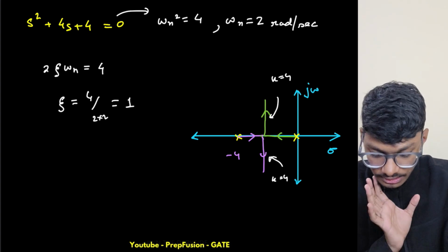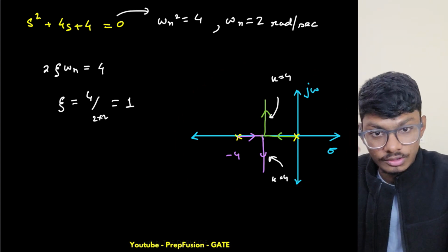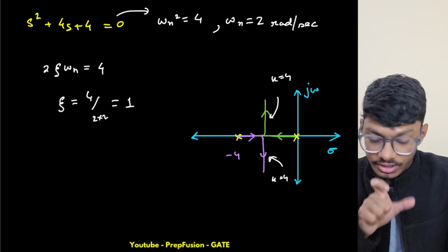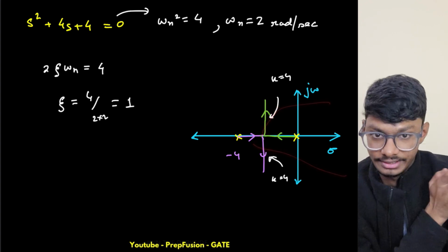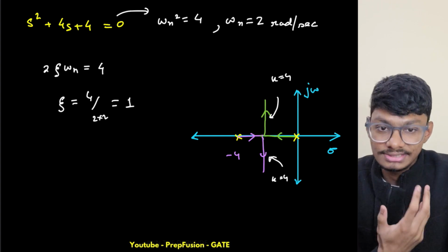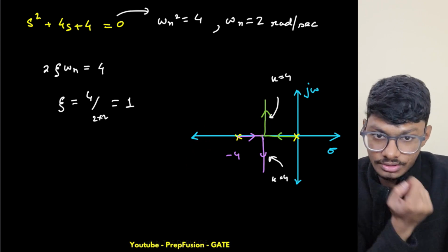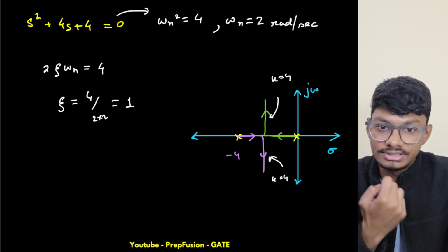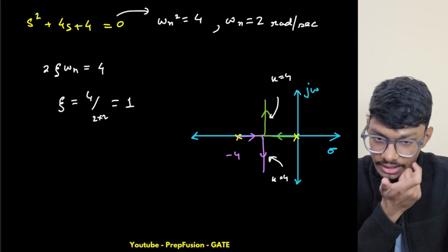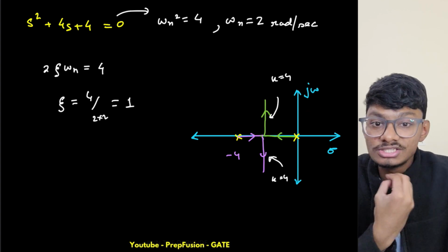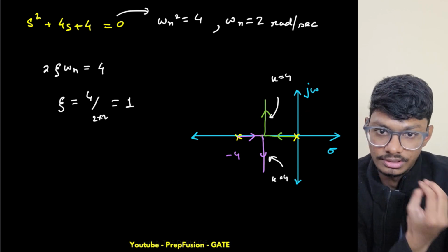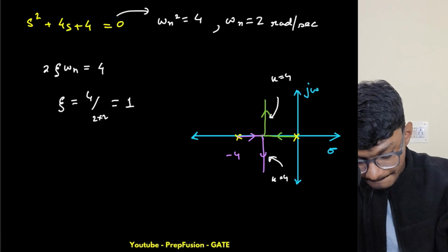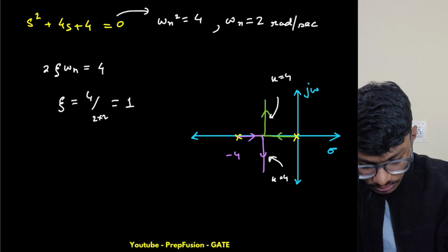Now this is my root locus. I have already told you what happens if I add further poles to the OLTF. What happens to the root locus? It shifts to the right. Now let us add a pole at s equals -10. Let me add a pole and let's see what is the effect on the time domain parameters. We know what happens to the stability: obviously, it tends to become more unstable. Now let's add a pole. This is 0.